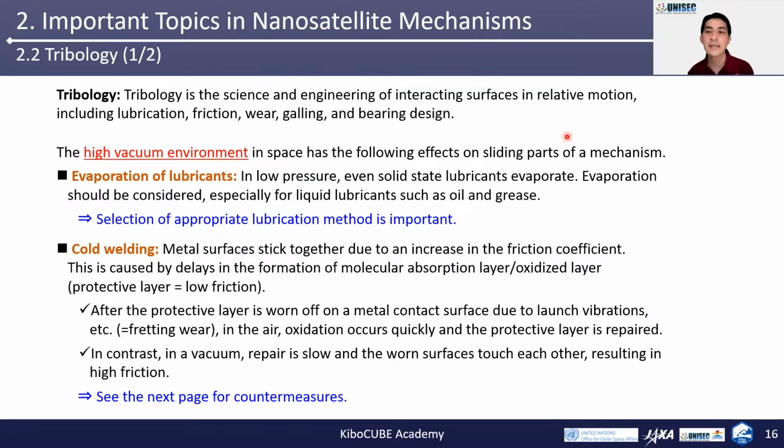Tribology is the science and engineering of interacting surfaces in relative motion, including lubrication, friction, wear, galling, and bearing design. The high vacuum environment in space has significant effects on sliding parts of the mechanism. First, there is evaporation of lubricants. At low pressure, even solid-state lubricants evaporate. Evaporation should be considered, especially for liquid lubricants, such as oil and grease. Thus, the selection of appropriate lubrication methods is important.